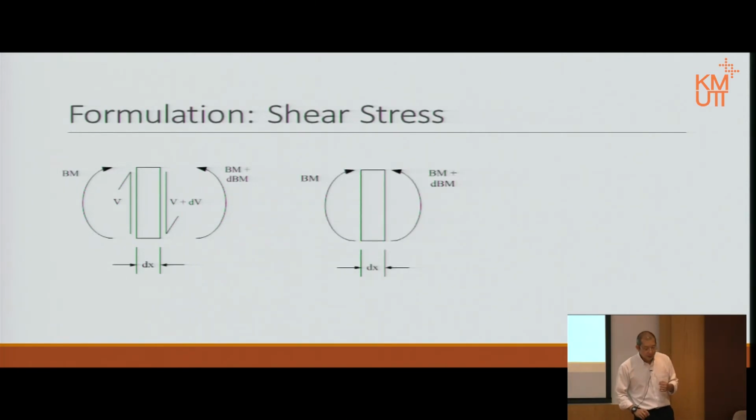Now, because we are not going to take sigma Fy, this one here is actually just to simplify the picture. This, I emphasize, is not a free body diagram. Here we can only use sigma Fx, because we haven't actually altered anything in the x direction. We cannot do sigma Fy because we ignore the shear. We cannot do the sigma moment because that shear also causes moment V dx. So only one equation is left in this picture, sigma Fx equal to 0, which is apparently enough.